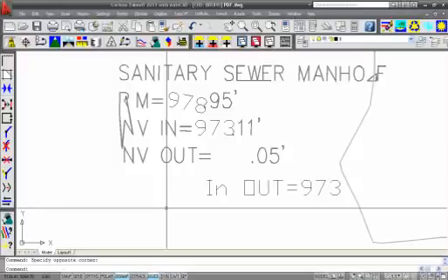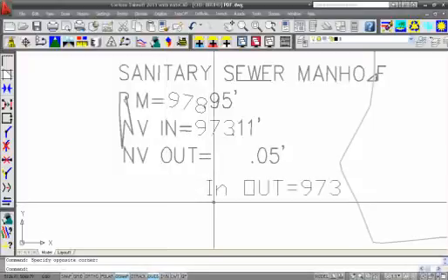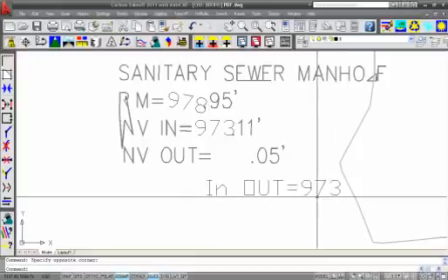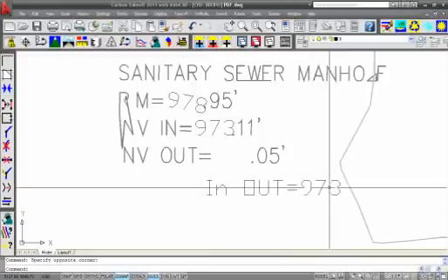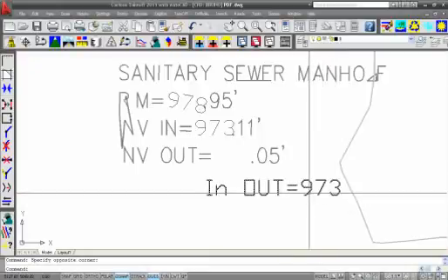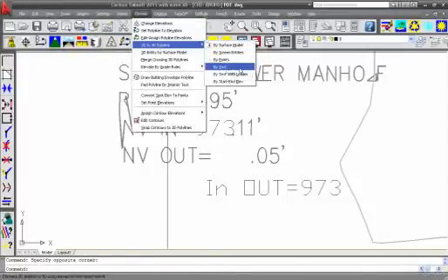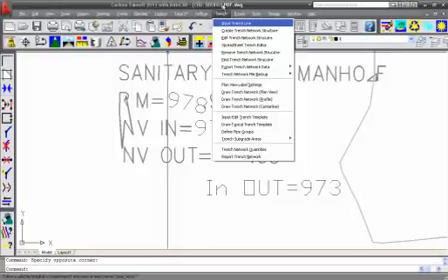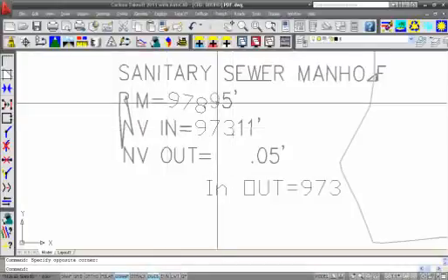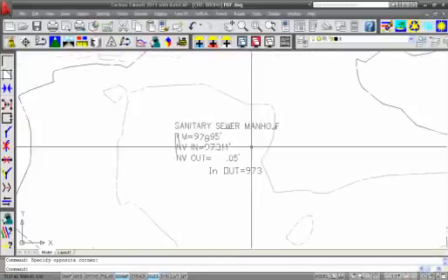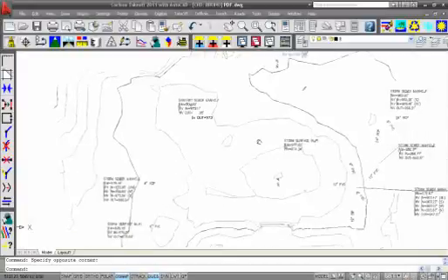So, yeah, say we had a lot of leader lines for a 3D line or a curve, we could convert all those leader lines into actual text and then run Elevate 2D to 3D by that text. Whereas before, that line work would just be dead to us. So we now have the ability to work off of that line work and convert it in the drawing.